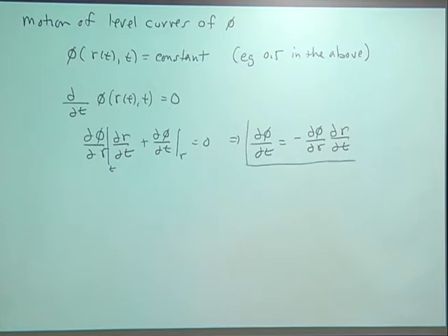Now this simple idea that we're doing here for a spherical particle, this is still a spherical particle here, you can write this in 3 dimensions just about as easily as I did here, and it's called the level set equation. This grew out of the applied mathematics community, and it's another interface tracking method where you don't track the sharp boundary, but you have a diffuse boundary of some sort that allows it to move in time and weld together topological changes.